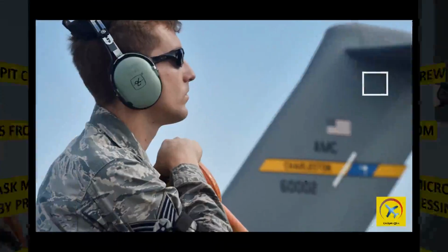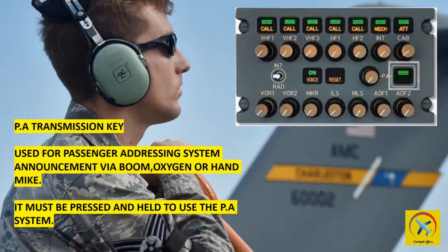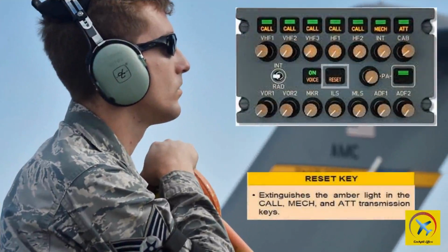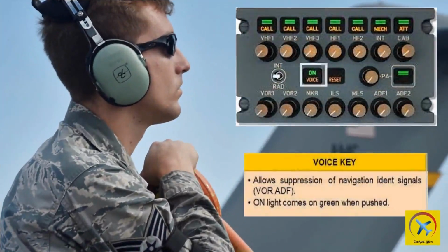PA button is used for PA transmission via boom, oxygen mask, or hand mic. The transmission button must be pressed and held to use the PA system. When the reset button is selected, it resets call, MEC, and ATT lights on the transmission buttons. When the on voice button is selected it inhibits ADF and VOR ident signals, and illuminates the on label a green color when pressed.